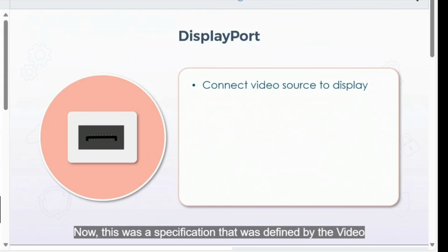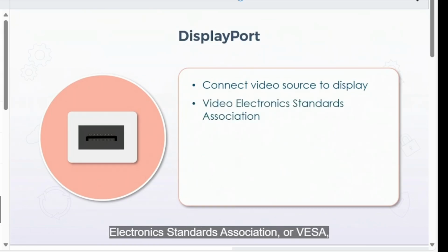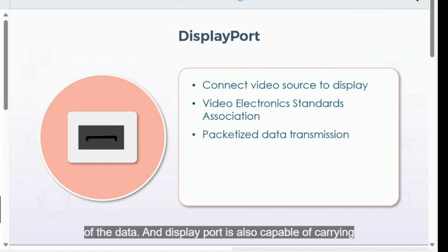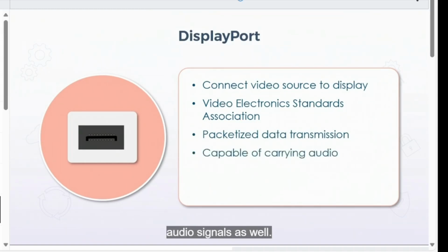Now, this was a specification that was defined by the Video Electronics Standards Association, or VESA, which is actually a very old association, but what it comes down to is that since it's a standard, it's not proprietary. So manufacturers don't have to pay any kind of licensing fee to put a DisplayPort on their device. In addition, DisplayPort uses packetized data transmissions very much like an Ethernet network, which can result in better flow control of the data. And DisplayPort is also capable of carrying audio signals as well.